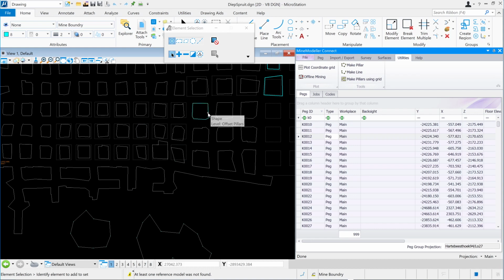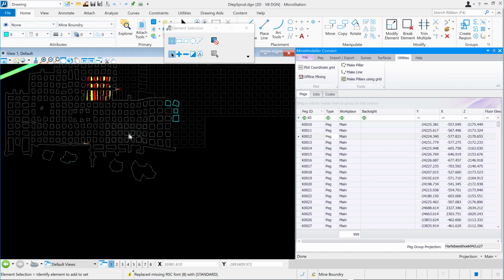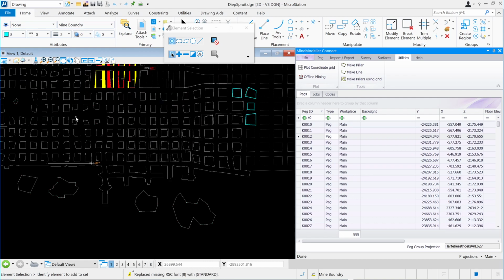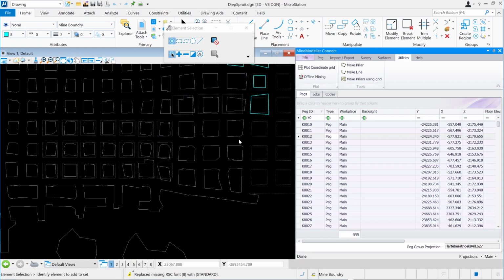So what typically one does in mining, I've made it a small area. Typically you do it over a huge area, over thousands of pillars. So what happens here is, you can see over here, these dotted rectangles are the planned pillars. That's what was planned in the mine plan, but then in the real world we get these particular pillars here. And of particular interest to miners is how far their deviation was from the planned pillars.